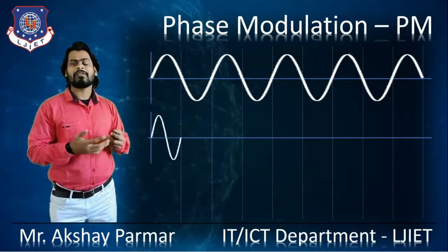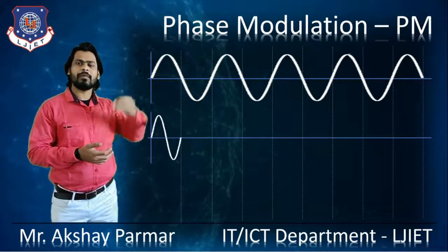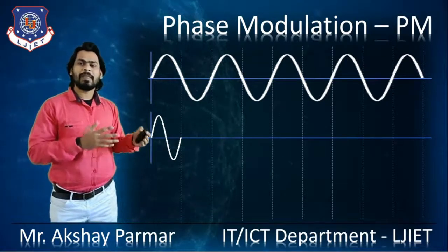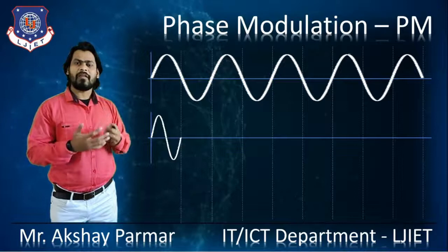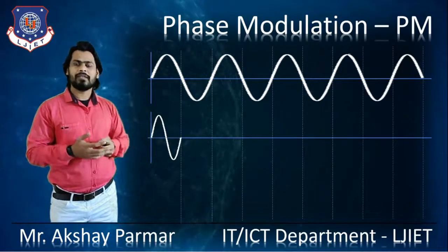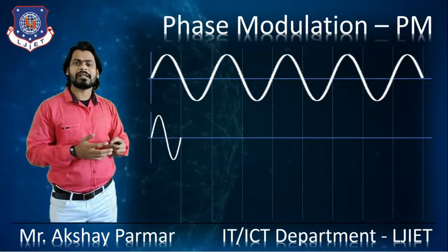So that's how we are representing that input signal with phase modulation, right? As we have discussed, for representing the positive side of the signal, we are using the signal which has the 0-degree phase difference. After that, to represent the negative side of the signal, we are using the 180-degree phase difference signal, right?